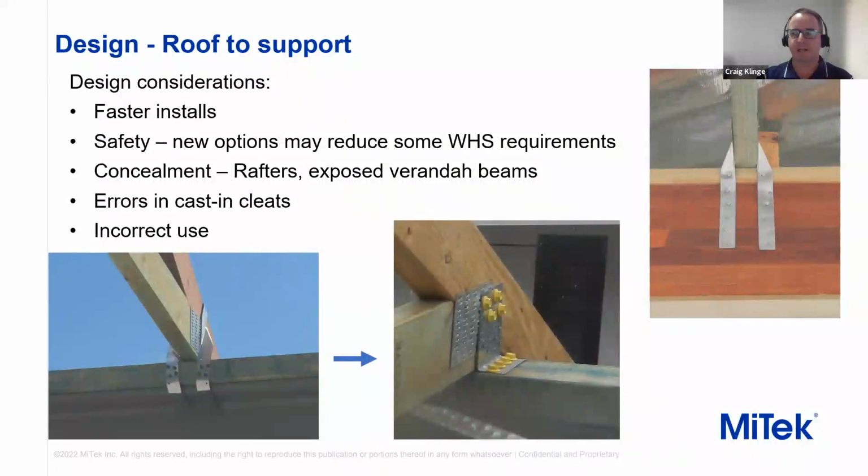We know the tie down's adequate. We've met all the requirements for the tie down, and we know that the result is engineeringly correct. Similar with the cyclone tie at the top right there, it's an unpunched strap, nailing in a nice pattern through it, so we know it's going to work. The only query I would have is whether the air pressure was probably slightly high with the way that it's impacted onto the strap itself.